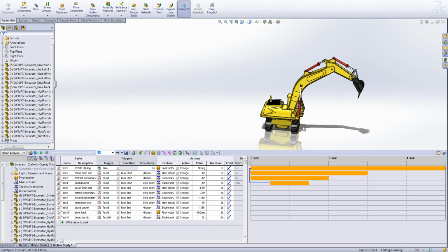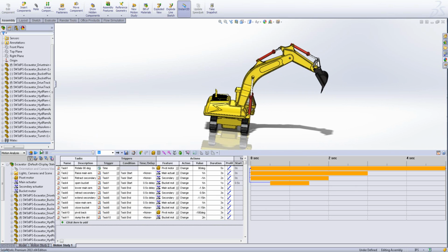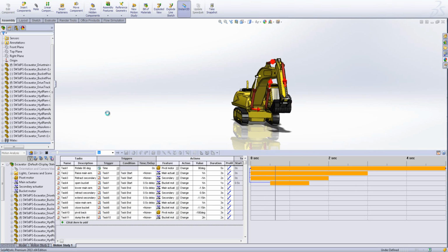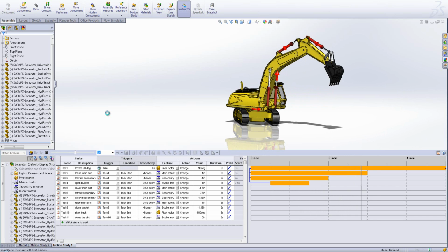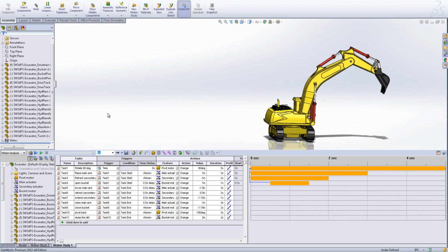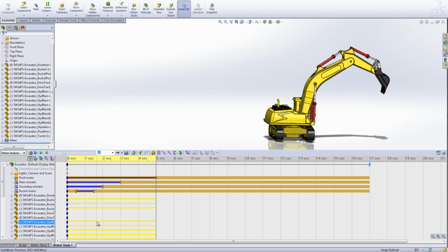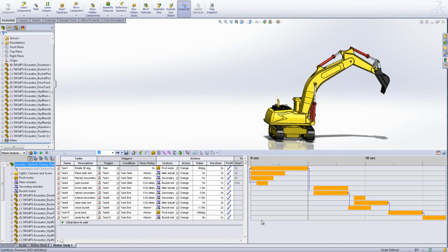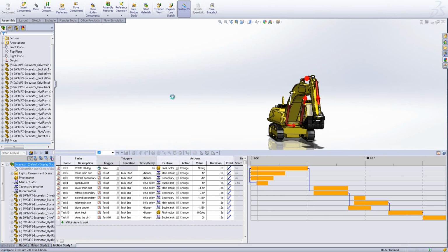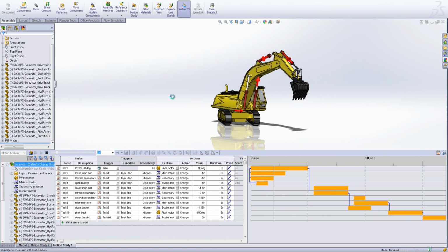So like so. And then finally all we need to do is click calculate, and SolidWorks will whip through and hopefully give us the result that we're after. Now you'll notice that that has stopped there, and it's worth bringing this to your attention now. SolidWorks will still be based upon the original motion study, so we've got our keyframe set to 5 seconds for the time being. So I'm going to drag that out to 17, and that's going to allow the study to be 17 seconds. So switching back to the event-based motion now, hopefully we will see a big difference in that it will run all the way through to the end.